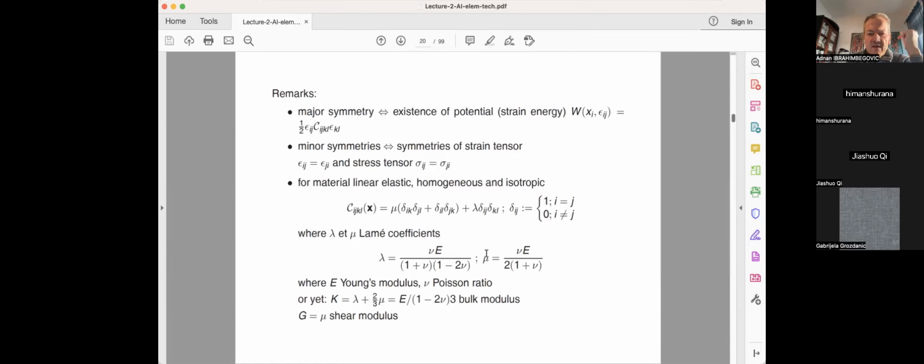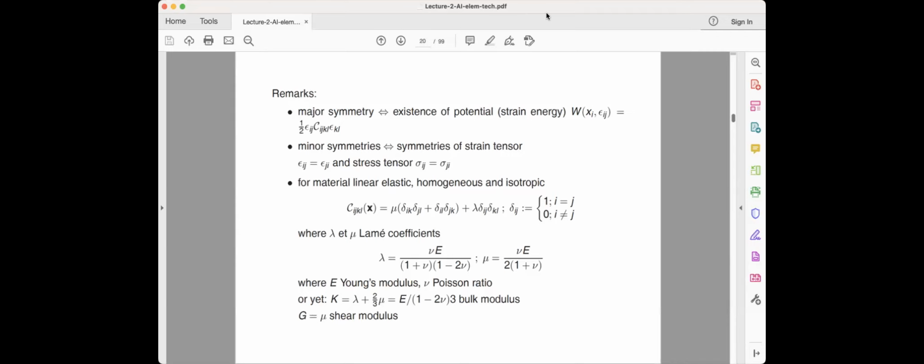So basically, you can quantify the behavior of the elastic material either by using these Lamé coefficients or Young's modulus and Poisson's ratio. In fact, I like to remember this in a very nice way. Say you have a typical specimen that you are testing, and here you apply some kind of force, let's say a sigma 1,1 type of situation.